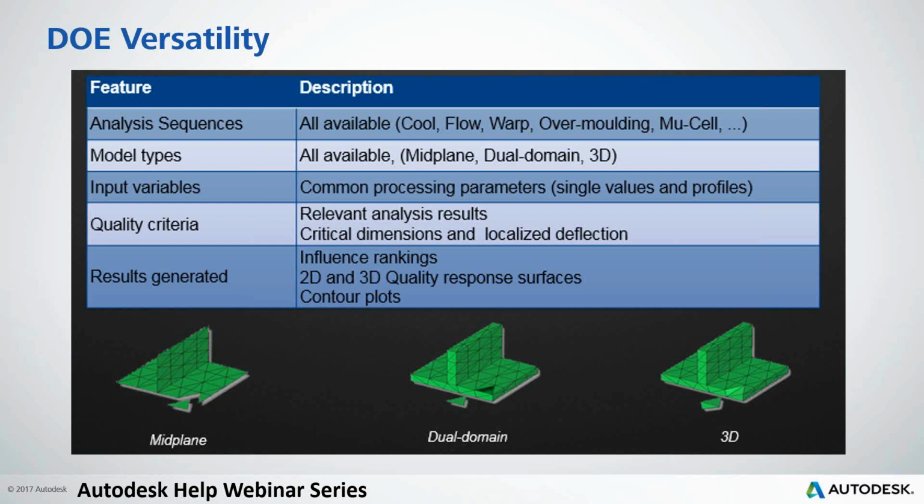Today, there's extensive versatility when performing a DOE in Moldflow Insight. A DOE can be used with all available analysis sequences, so, for example, with cool, flow, overmolding, and MuCell. A DOE can also be performed with all model types, so that would be with your midplane, your dual domain, and your 3D meshes. DOEs can be used with common input variables, both single values and profiles.